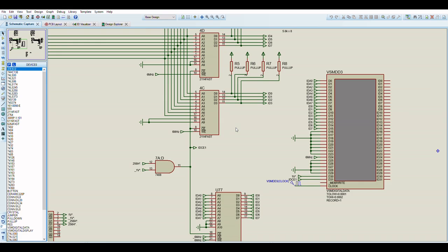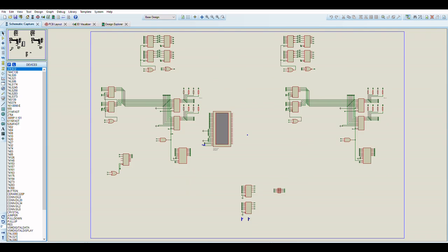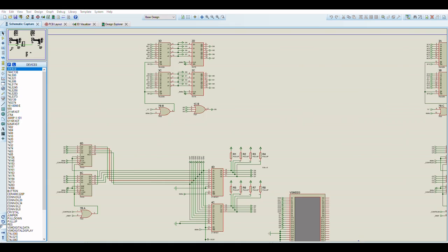We can see, for example, when the full line starts at 180 horizontal pixel position and then goes to 002FF. It gives us 384 pixel clocks per line. 256 of those pixel clocks are used during the output phase of rendering pixels to the analog circuitry.